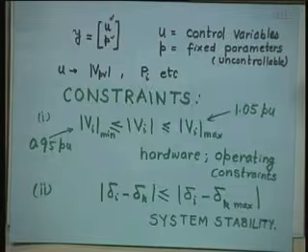So, you have to bring it back. How do you bring it back? By controlling real power, you can control it. The generation power can be controlled by controlling the steam input. I do not know whether you have studied automatic generation control, which you must have studied in your undergraduate, and you must have seen that if you increase the steam, power output increases. If you decrease the steam, power output decreases.